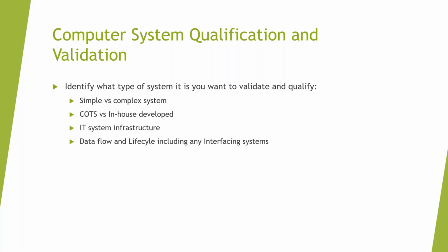Okay, so thanks, John. We want to talk to you about computer system qualification and validation. So as John mentioned earlier, computerized systems need to be validated in order to give assurance of data integrity maintenance. So as an auditor, I want to understand how the computer system validation has been performed. And if so, what standards did they follow and apply, and how was the CSV and qualification performed? By understanding how an organisation has applied and performed CSV and system qualification, I can assess whether the data has likely been generated and managed in a manner which will assure maintenance of data integrity.